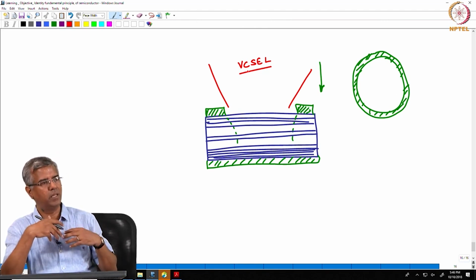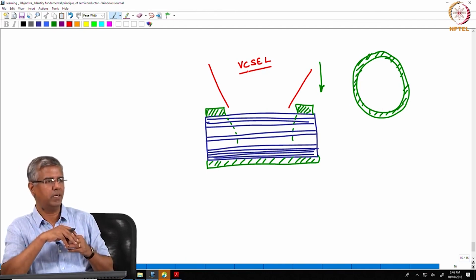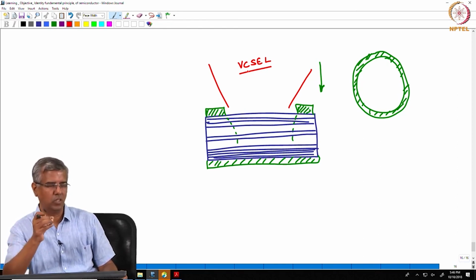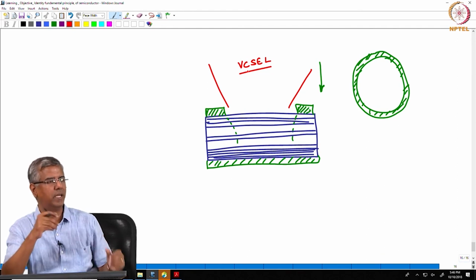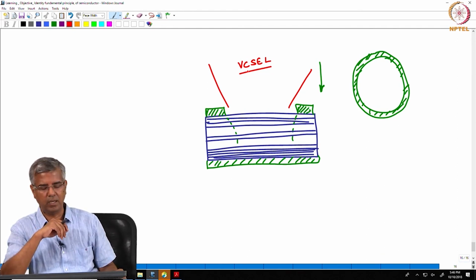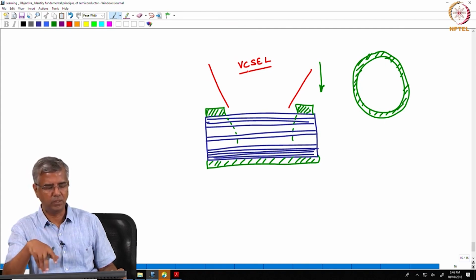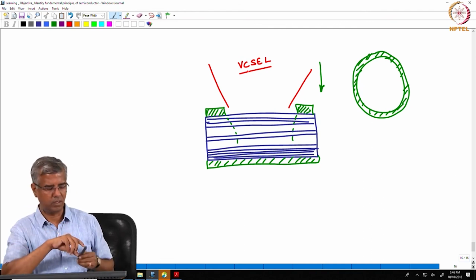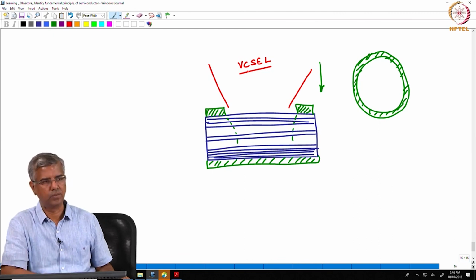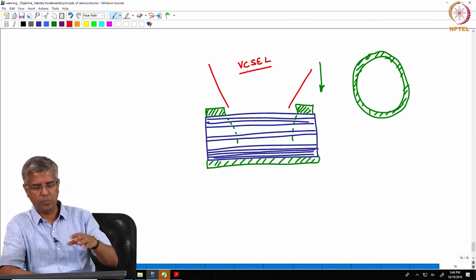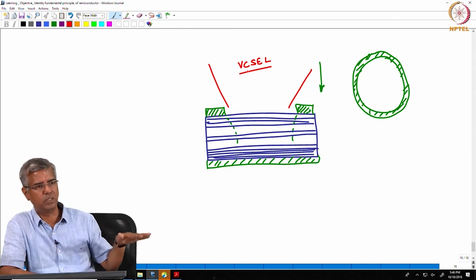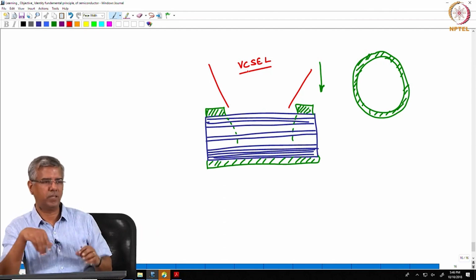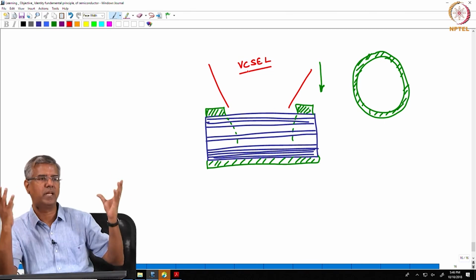So, that actually means that you can couple it easily into an optical fiber, typically a multimode fiber, unless you define the ring structure to be very, very small, so that light emission can be single moded. But you get very nice circular beams out of these VCSELs, right. So, those are good for certain applications. That is the top electrode, and then you have the bottom electrode, which is totally planar. No, the bottom electrode can be continuous. Top electrode, a ring only to define an aperture through which light can escape.